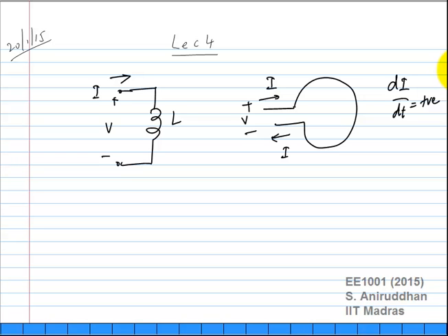If you remember, we had done the power and energy calculations for the capacitor. I just gave you the final answer for an inductor. I hope all of you did this. If you did it, you will see why it needs to be in this direction. Because when you have a positive di by dt, you are basically putting energy into the inductor to set up the magnetic field. That is half Li squared. I hope all of you have confirmed that for yourself.